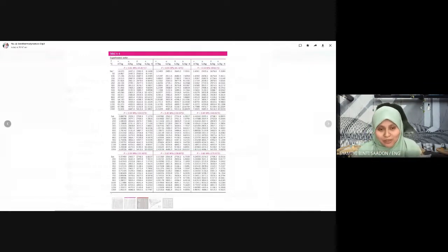That's why we need to learn first the properties, the definitions, etc. The substance is water, H2O, but it is in superheated form. So superheated must be a vapor. It cannot be a liquid. Superheated water is vapor, so no need to define HF or HG or the quality x.